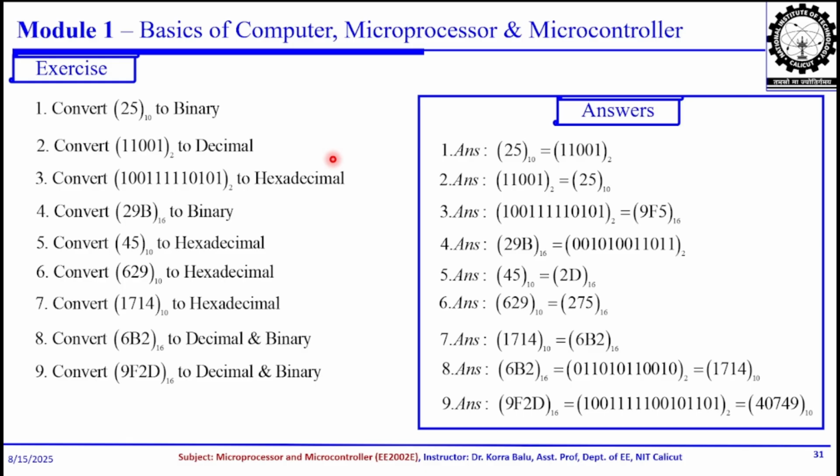Then you will face the problem of whether to go for positional weight calculations or for division. The simplest way to represent it: if a conversion table exists on your left side, the most significant side, that is MSB, for example hexadecimal to decimal, where the right side LSB, the decimal, does not have a conversion table, you go for the positional weights. That is hexadecimal to decimal: positional weight.